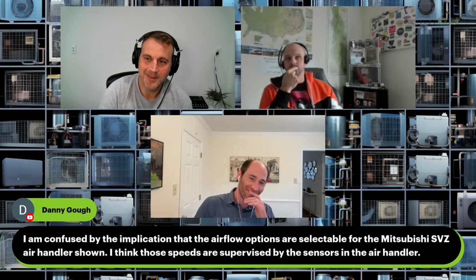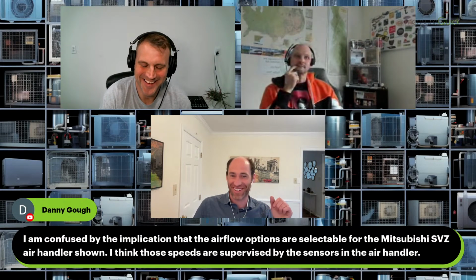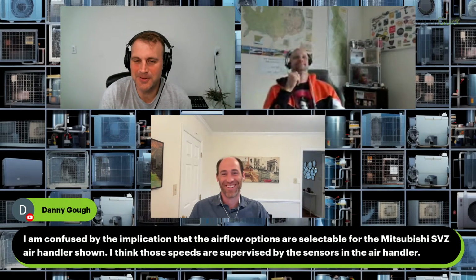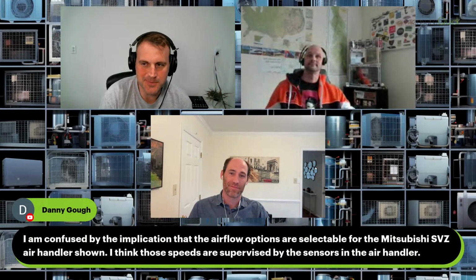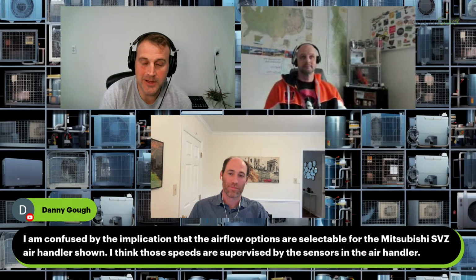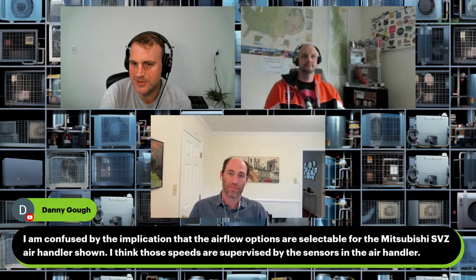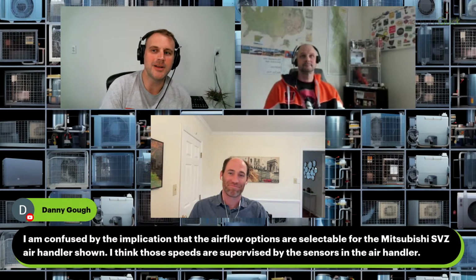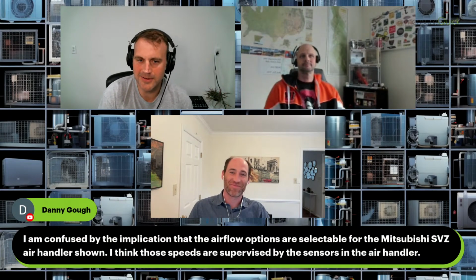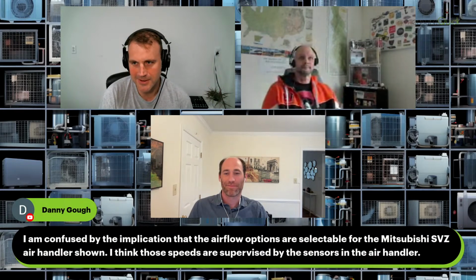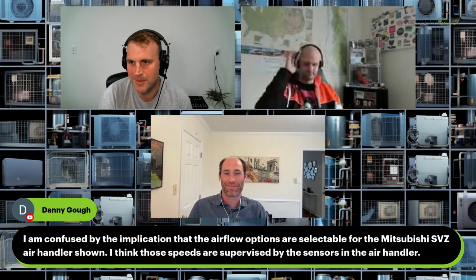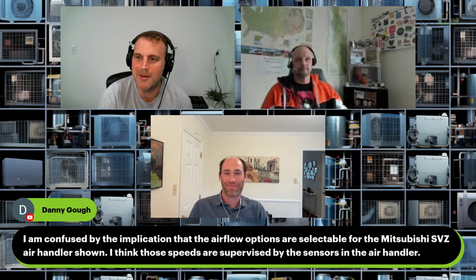You're not the only one confused by Mitsubishi's control of their air handlers. Yeah. So this is where the data is just not transparent enough. In their submittal sheet, it shows the three flows and it shows one sensible heat ratio number. Does that mean I can get the same sensible heat ratio at all three flows at the same conditions? Because that's what I'm potentially thinking. Is my EEV going to modulate and make that happen for me? I guess so. This is where we don't have enough data from manufacturers.